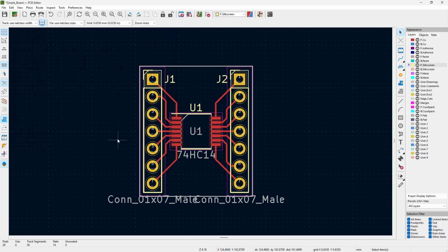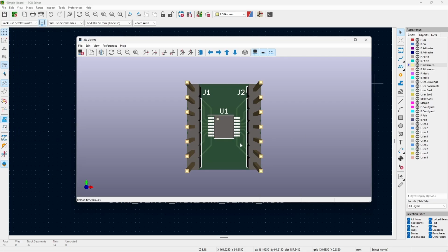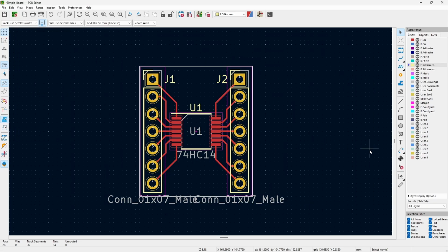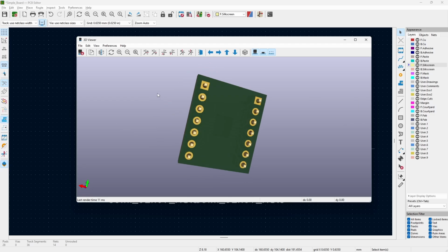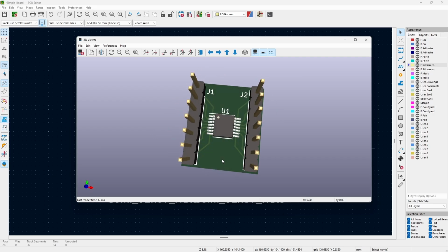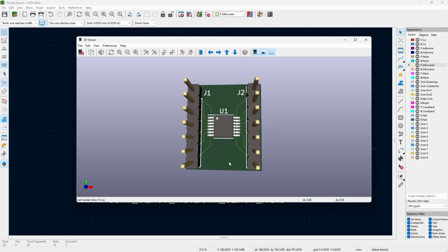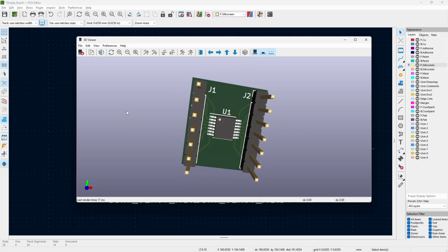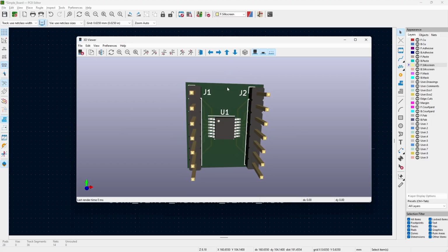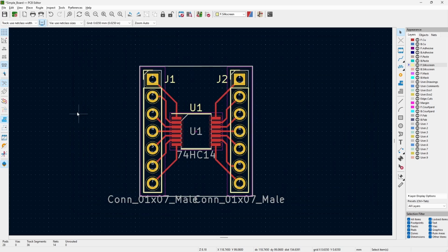So now finally we have our board, and we can take a look at it again just to double check, make sure everything's pretty in the way we want it. It looks exactly the way I would expect. Nothing on the back because I didn't put anything on the back. This could be done with a single layer board essentially, but I'm probably going to mount the headers the other way around, but I want the silk screen on the top. So when I ordered this, it would be a blank board. So now let's see exactly how you can generate the Gerbers to order this.